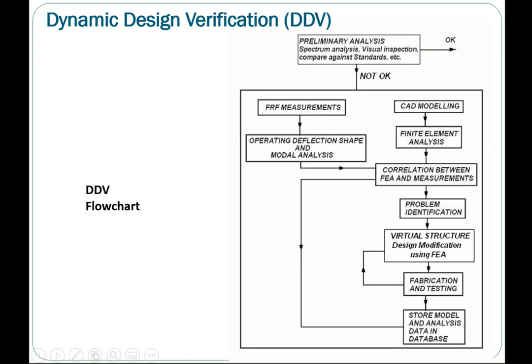So through modal analysis, right? Modal analysis tells us the dynamic behaviors or dynamic characteristics of that particular machine. So for the model itself, if you perform finite element analysis, you can perform computational modal analysis, which will give you a set of natural frequencies and mode shapes. This set of natural frequencies and mode shapes is of your CAD model itself. By right, it should behave the same as the actual.